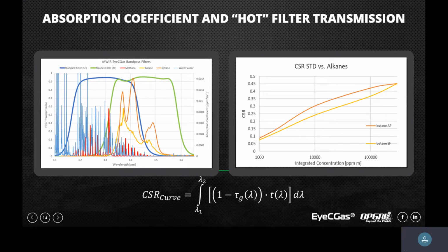We have a lot of interference from water vapor, and on hot, humid days in Houston, it becomes an issue, and in other places in the world. Only when you get away; in close range, it's negligible, as I said. But if you go further, the contrast that you see in the camera between the temperatures is almost diminished, and I'll show you anyway.